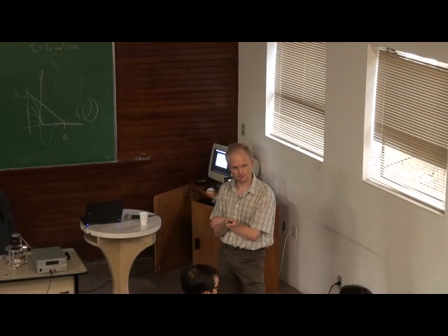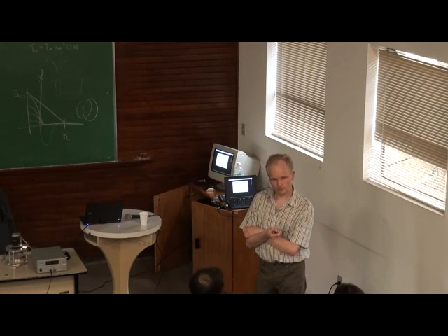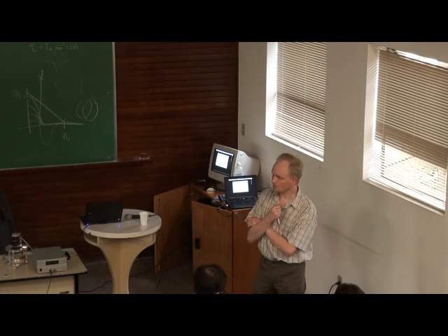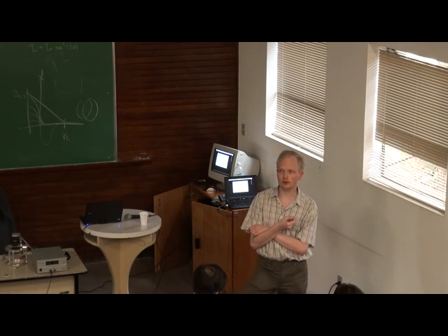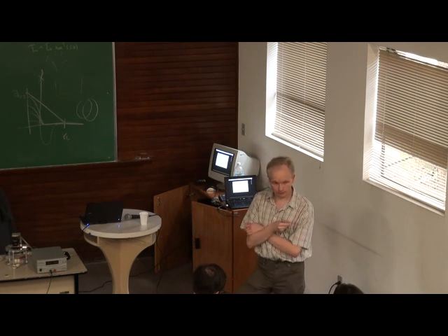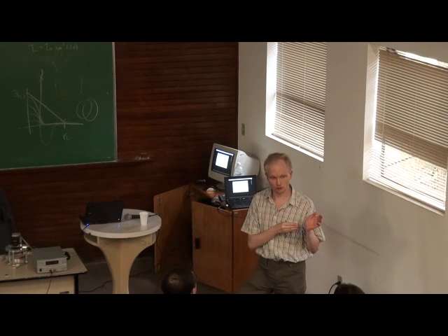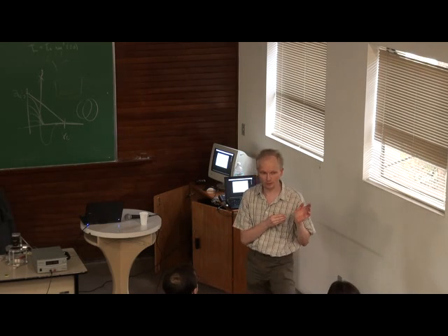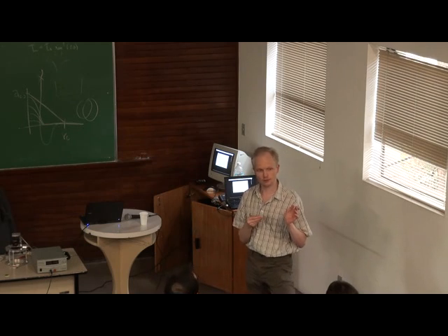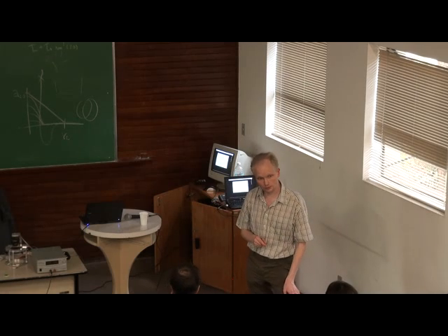What about the force field? What kind do you have? Do you have, for example, a mixture of the gas, or do you have your own force field? If you want to use AMBER or these other well-known force fields, I would use GROMACS instead to run such simulations because I think it's better integrated. But to tell you the truth, I'm not sure how well integrated AMBER and CHARMM are with LAMMPS. I think you can do simulations, but you might as well download a code that makes it easier to run these kinds of simulations.